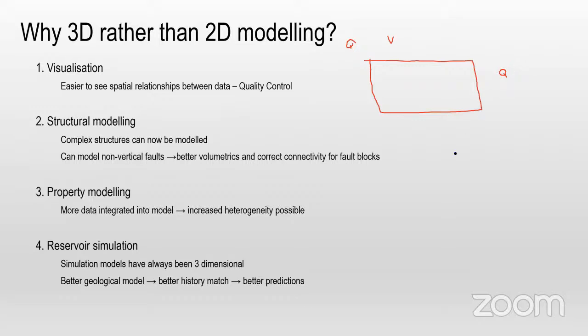Multiplying A, the area of the reservoir or field, by H, they found the volume. If they multiplied it by phi, they could calculate the pore volume, and if they divided this by Bo, the volume factor, they could find the stock tank oil volume in the reservoir.